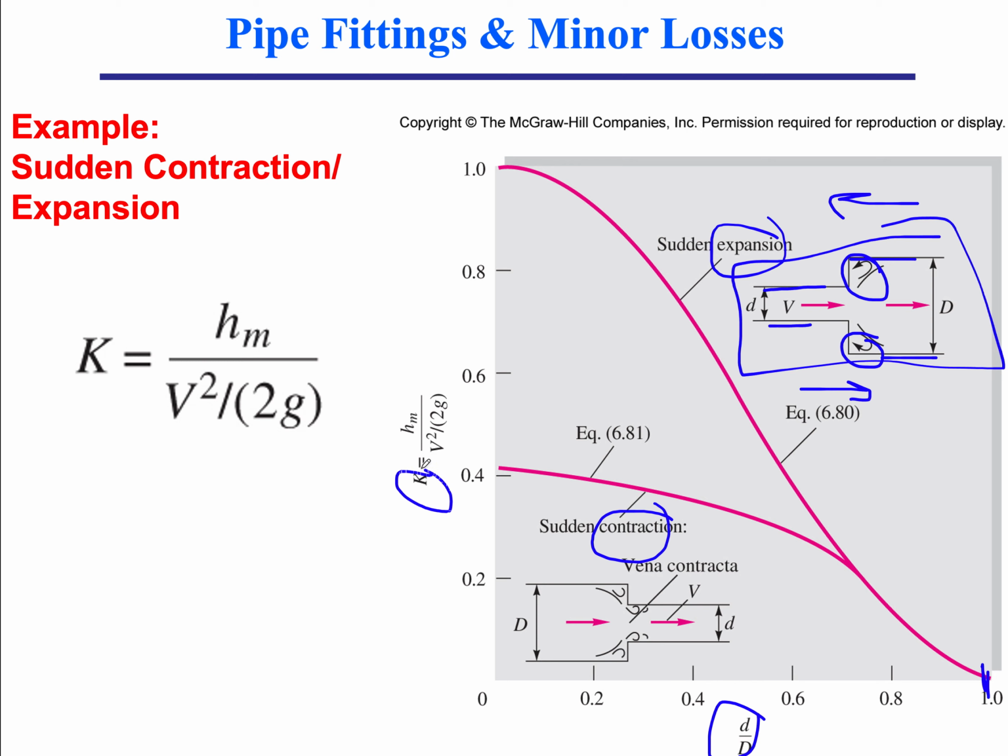So your K, your dimensionless friction factor for this expansion or contraction, is going higher. And we see that in the case of a contraction. In this case, you would guess the opposite, but for a certain diameter ratio, a contraction would have almost half the friction head loss at that same speed and same geometry.